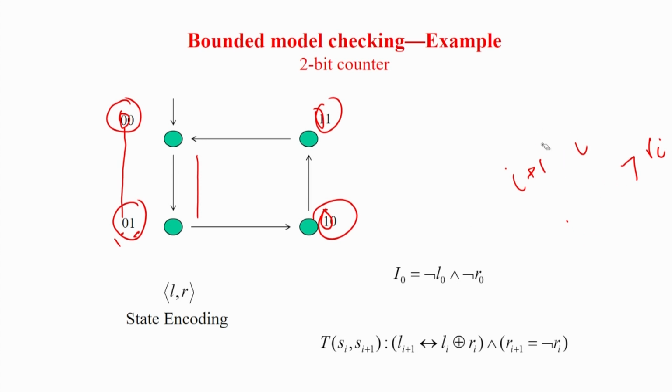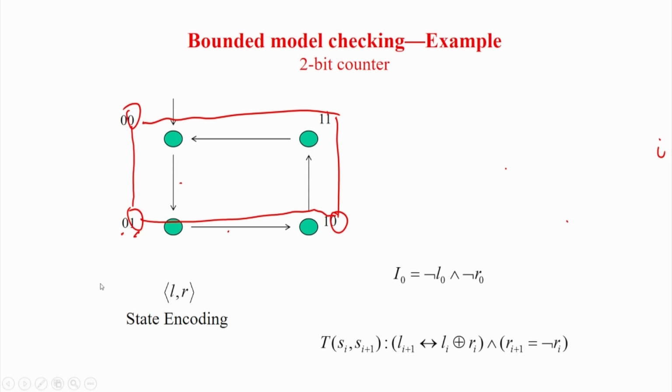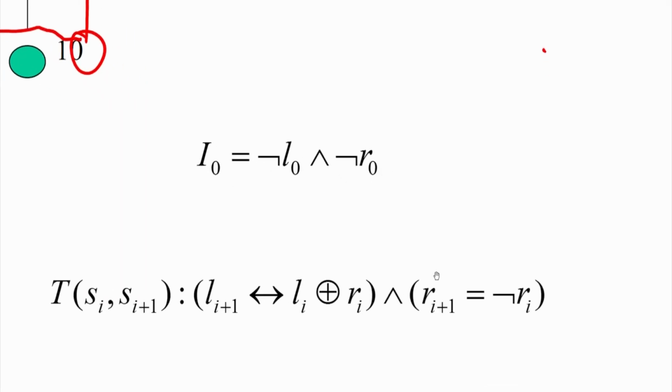But there is another way of writing, which I am showing over here, because it will be more compact. If you write it the way I have shown for symbolic model checking, then you have to model all 4 in that fashion. Another way of doing it is the observation I showed you: the MSB is 1 if and only if the previous state bits XOR to 1. And the LSB, if you see, is toggling: 0 1 0 1 0 1. Therefore, there is another way of writing this expression. Both ways are similar, the symbolic model checking way as I have told you, or this one.